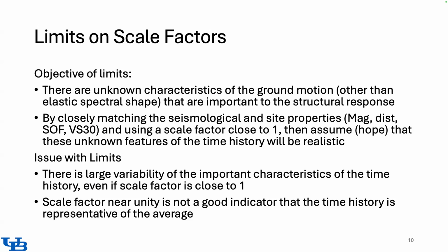Typically, there is the belief that we shouldn't use very large scaling factors because there are other processes that we may not have well characterized for the ground motions. So when we are applying very large scaling factors, we are influencing that.